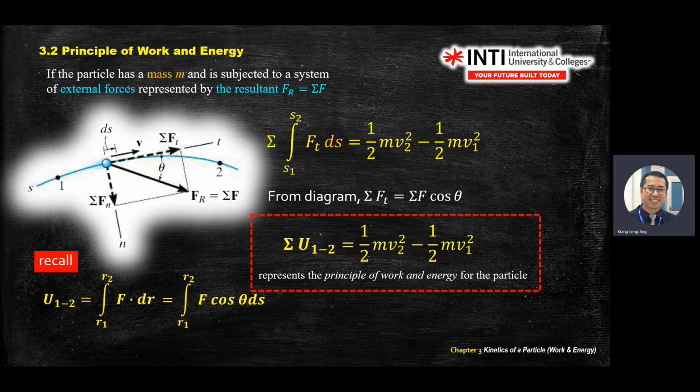In this case, what is the energy? In this case, the object is moving, and without any reference of height, then it falls under kinetic energy. You only deal with two energies in this module, kinetic and potential energy. Potential, you know that it deals with gravitational acceleration and h. This diagram or this object does not have h. There's no change of elevation, so you don't need to consider potential energy in your calculation under principle of work and energy.